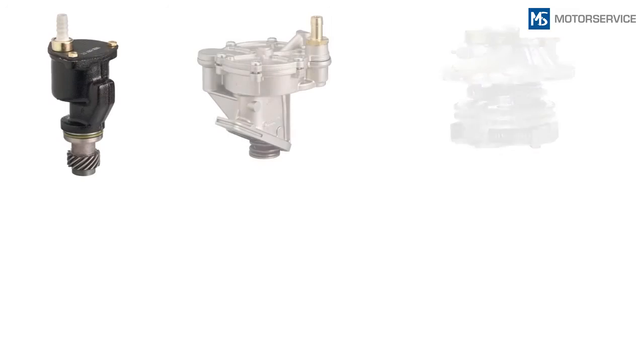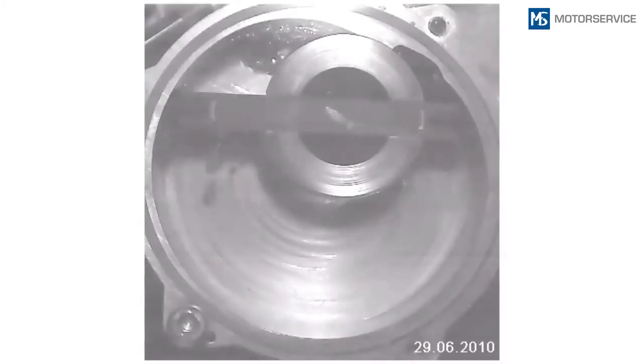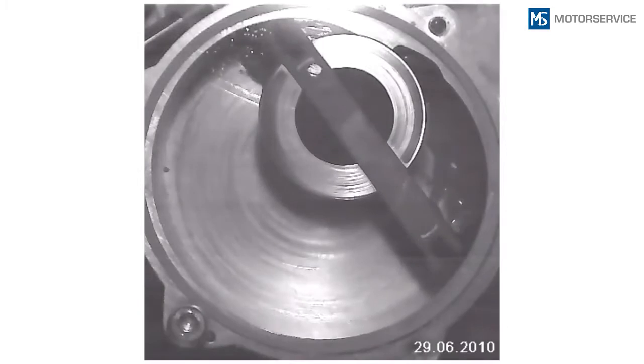Vacuum pumps can be driven by means of cams, tappets, chains, belts or cam discs. Single vane vacuum pumps constitute the latest technology and in many cases are installed on the cylinder head and driven by the camshaft. The aspirated air is generally conveyed into the cylinder head. This high-speed intake into a single-vane vacuum pump provides some idea of the stresses that occur during operation.